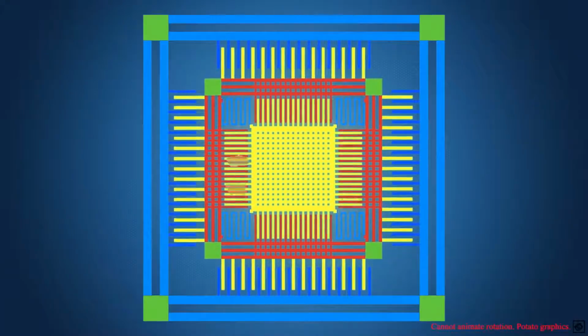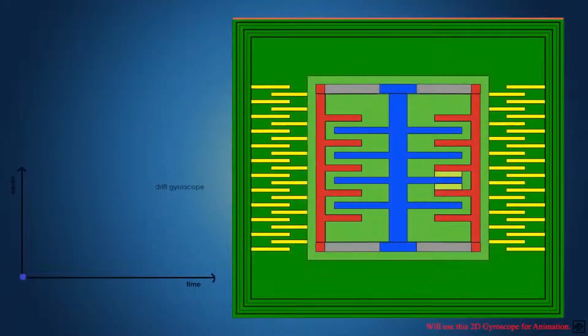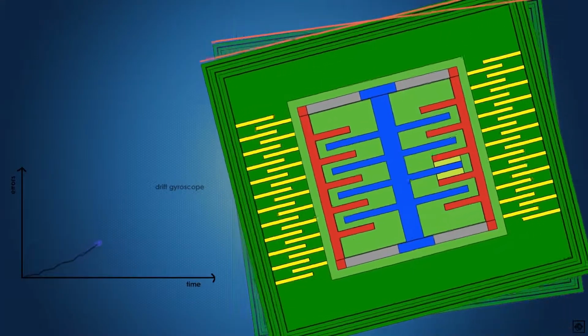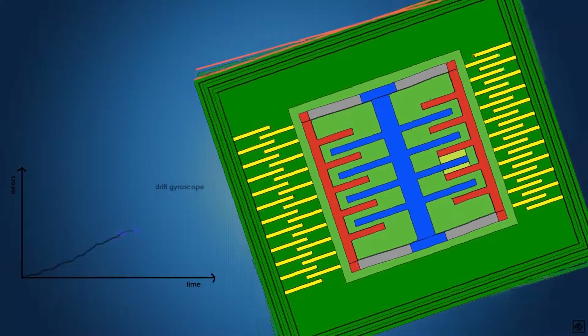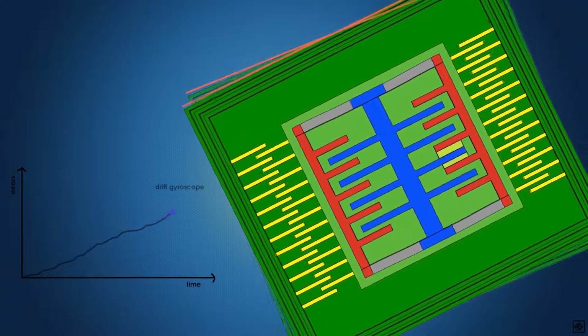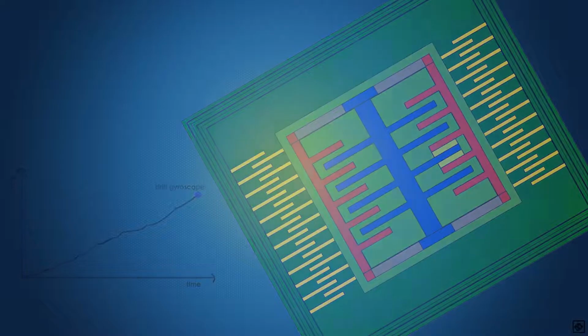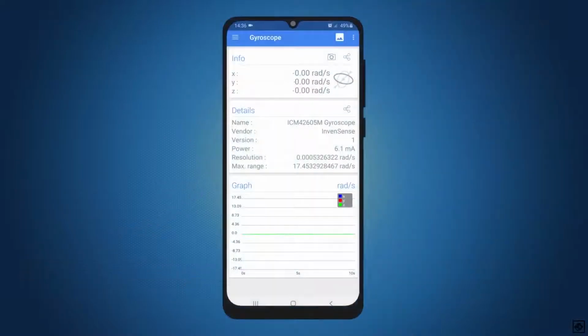So using the gyroscope, the phone can detect how much it has rotated over which axis and process that. But the gyroscope is not affected by gravity, it has to reference its position on itself. The current rotation is based on the previous rotation added with the detected change in rotation. Over time errors will add up. Hence, drift will occur. The gyroscope itself is not enough to calculate the true rotation of the phone.